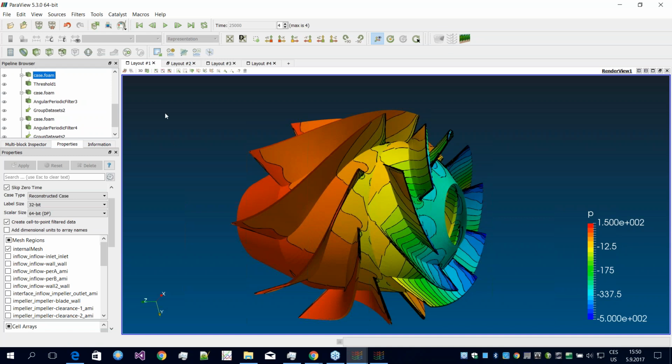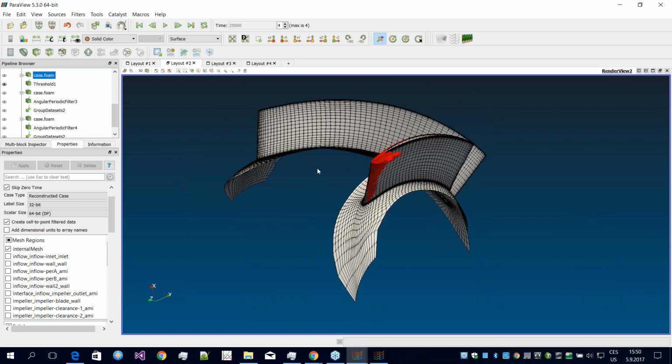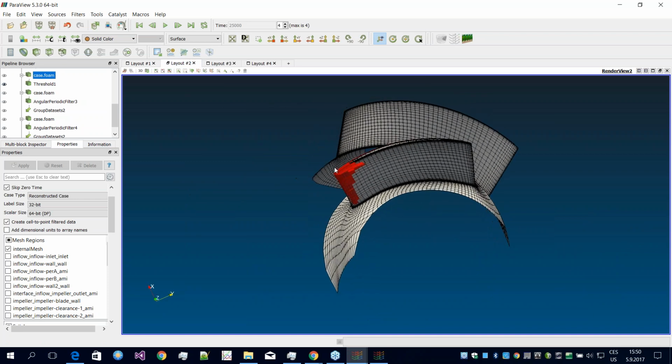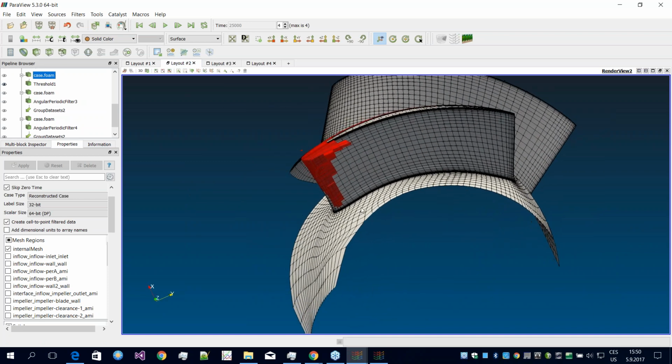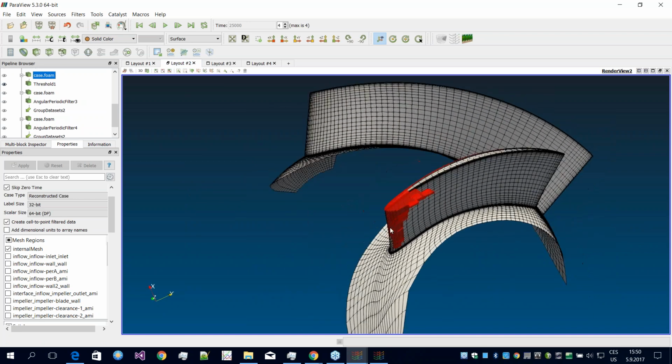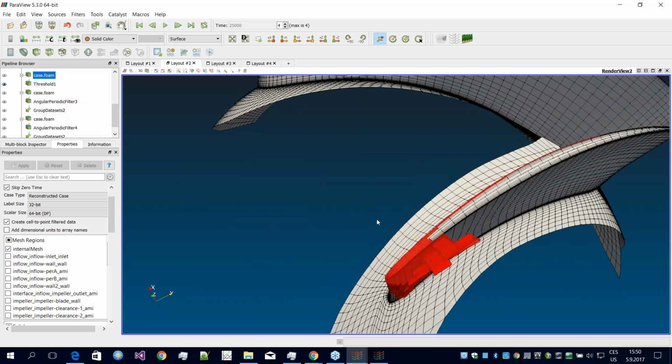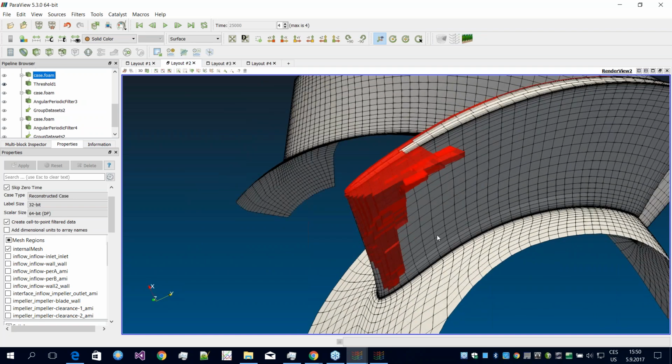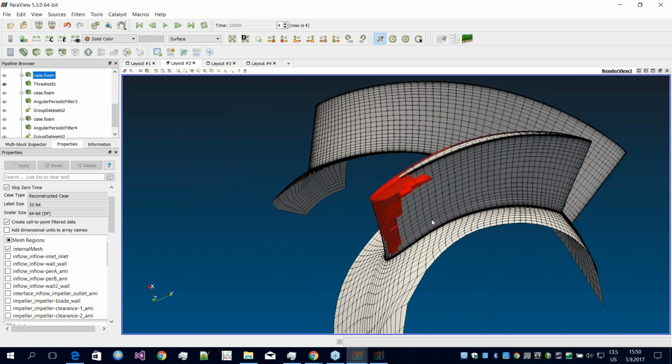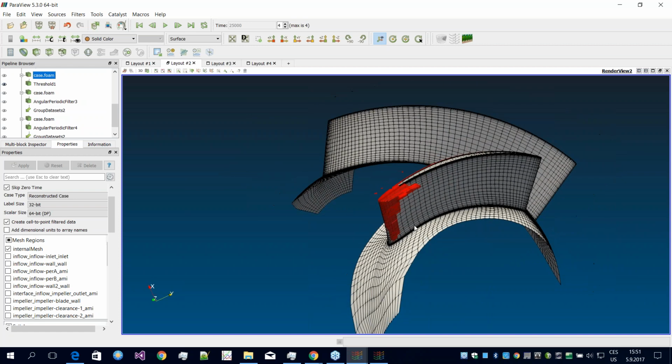So this is the meridional average and turbo unwrap. And last but not least, because we have enabled the cavitation risk, we can visualize the blades or the cells in which the cavitation risk is positive, let's say. So you can nicely analyze the places in which the cavitation occurs.